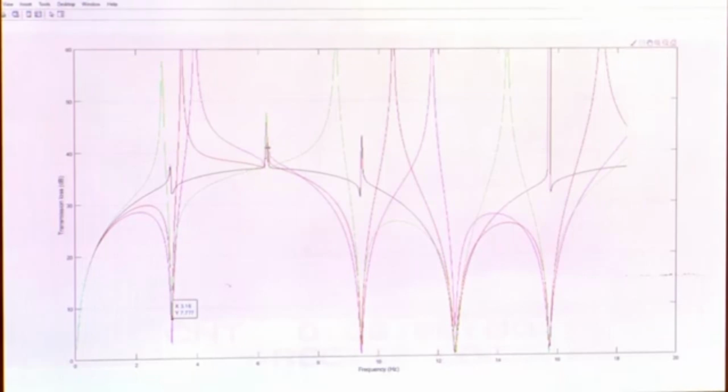If we choose a length different from L by 4, we will see a sharp trough occurring here. Also notice that when you are getting a peak here, where I am pointing my mouse, you are also getting a peak somewhere here, that is your third one. So, we are able to cancel two troughs, the trough due to the first axial resonance and the third axial resonance, but the fourth one is not improved even with the L by 4 extension, though the fifth one we can improve. So, this is what we basically get by this extension.